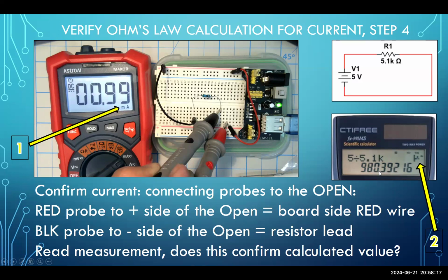The decimal point preceded by no more than 3 digits, and the appropriate engineering prefix shown right there. That's proper engineering notation. Your calculator shows you this with the metric prefix 0.99 milli. I'm going to show you in just a moment 0.99 milli is in fact something very close to 990 micro.